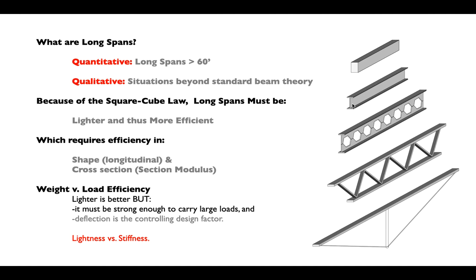So the logic of an I-beam, or a W shape, is that we're really deploying that material where it's going to work the hardest, in the flanges, the areas of greatest tension and compression. And the I-beam shape is based on putting as much material at the far edges, remember the farthest fiber of the beam, as we can, and minimizing the amount of material in the web, in the kind of lazy area closer to the neutral axis.